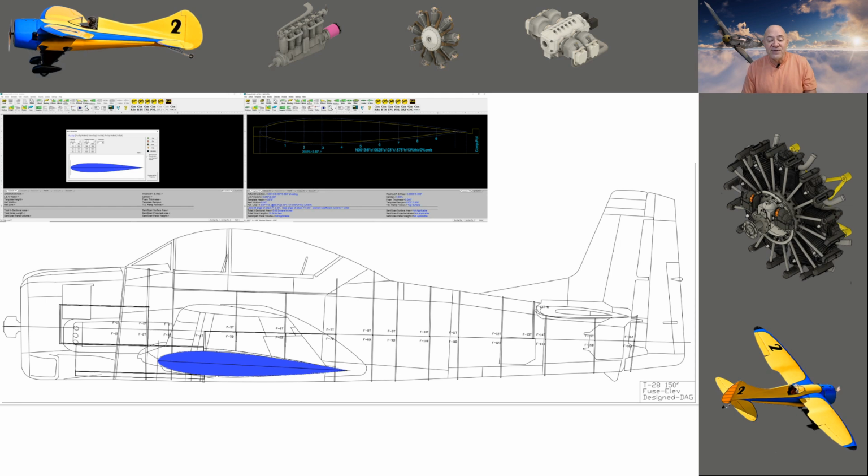The reason I'm doing this is I want this airplane to go fast. I'm going to put about 15,000 watts of power in this. It should do about 120 mile an hour level flight, and that's fast for a 150-inch wing airplane. But the reason I did this fully symmetrical is because as I'm going fast, I won't be having to hold quite as much down elevator.